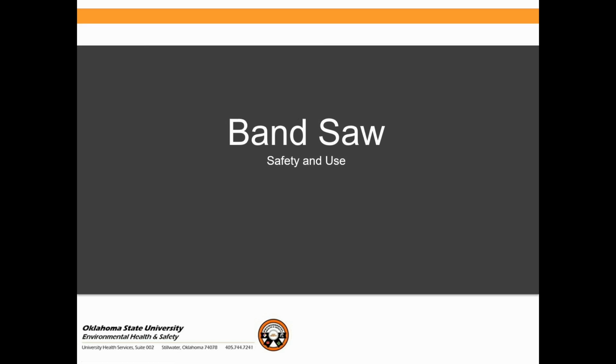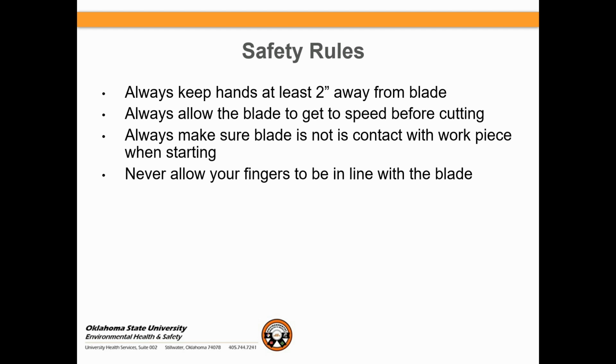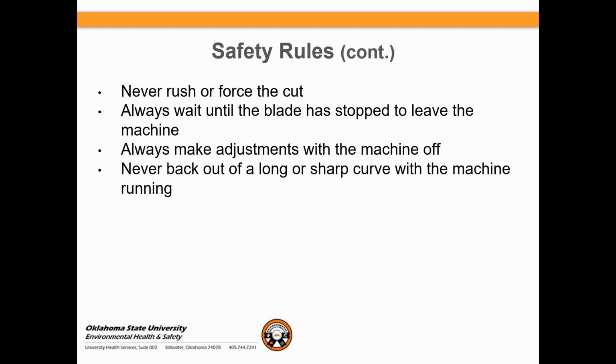Let's talk about bandsaws real quickly. Always keep hands at least 2 inches away from the blade. Always allow the blade to get up to speed before cutting. Always make sure the blade is not in contact with the workpiece when starting. And never allow your fingers to be in the line of the blade path of travel.